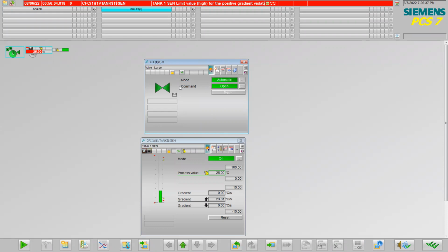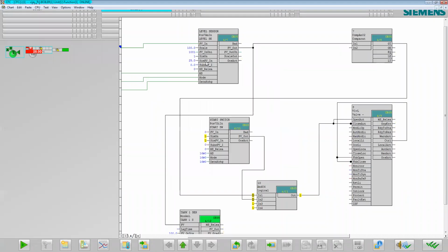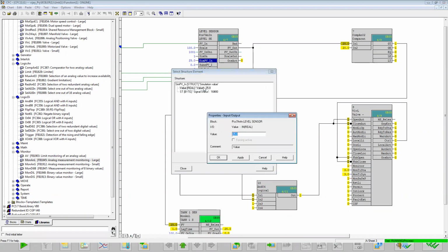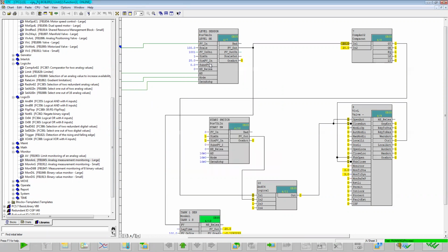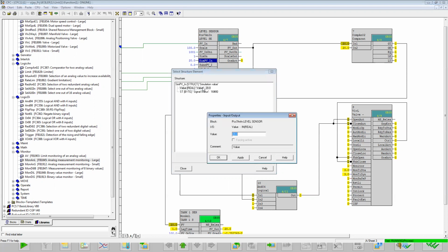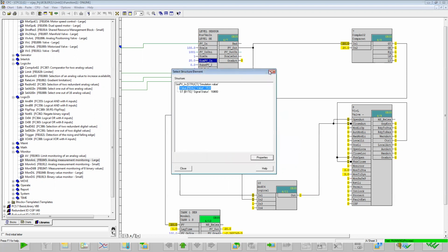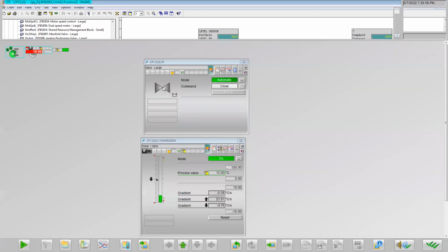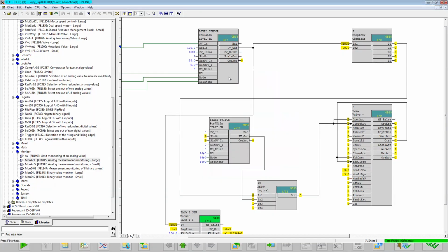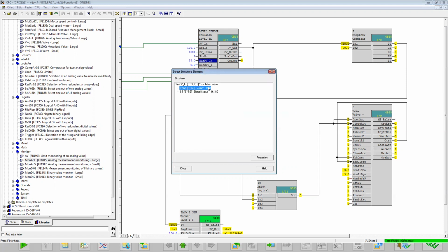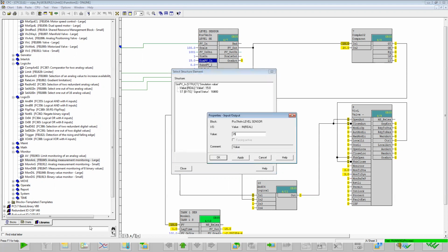Once the tank level goes less than 25, for example, to something like 20, okay, greater than 20 only we have fixed. So if we put it as 15, automatically your valve goes off. When this goes above 25, now I'm going to 35, the valve goes on.